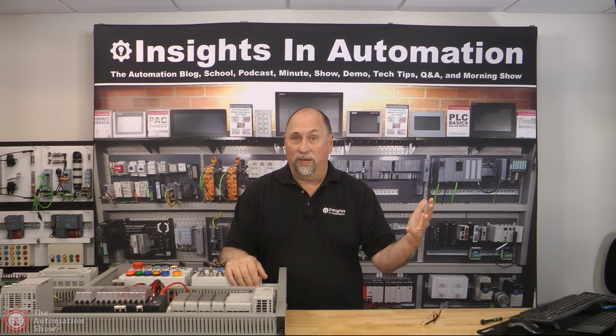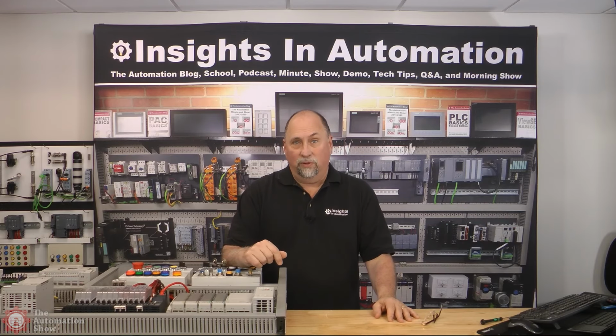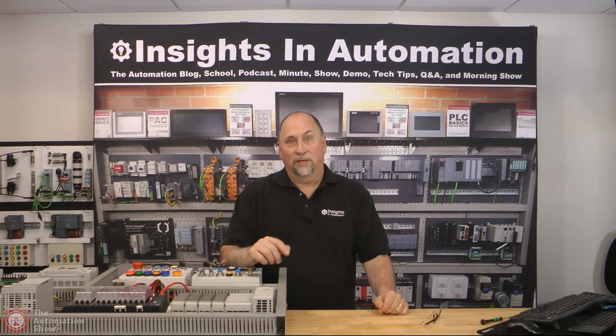You walked through it with me. There's a couple of things you have to know. Just turning on Ethernet IP is not enough. If you're going to use it on Ethernet IP, you also have to make the primary field bus Ethernet IP. And the other thing is, you're probably not, but if you had 192.168 as a Class B network in your building, then you'll have to change the IP address for the USB port.